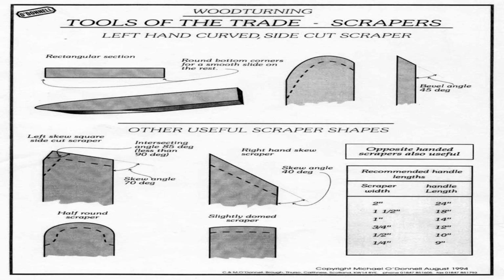And most scrapers are used on end grain instead of side grain, so if you're doing an inside of a bowl, there are people that scrape the inside of a bowl because it tends to work really well. I don't recommend a lot of usage of scrapers on side grain. You don't get as nice a cut. You get a really nice good cut on end grain. So, any questions on scrapers?